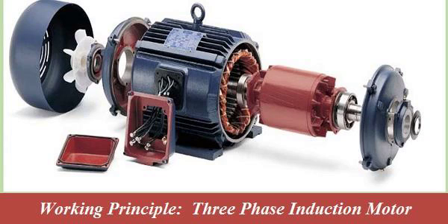Slip. In practical applications, the rotor never reaches the synchronous speed of the rotating magnetic field. The difference between the synchronous speed and the actual rotor speed is called slip. Slip allows the motor to produce torque and do useful work.